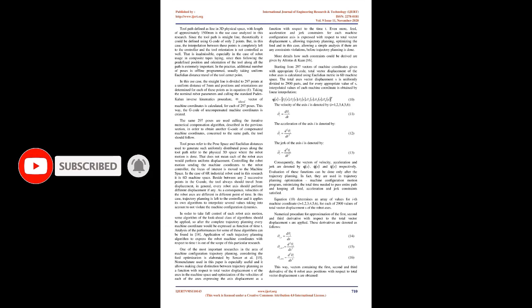No matter what kind of calibration algorithm is applied, a new set of calibrated parameters is obtained, and they differ from the nominal parameters. Also, these calibrated values of the parameters cannot be simply substituted in the same inverse kinematics procedure, since with changed parameter values, the assumptions of parallelism, orthogonality and concurrency are not valid anymore. Because of that, an iterative numerical compensation algorithm is designed in order to calculate compensated machine coordinates appropriate to the given desired pose, using the new set of calibrated values of the robot parameters.